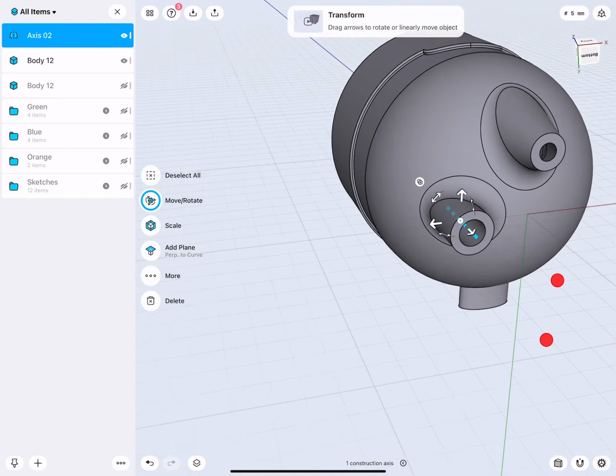Also here, I will extrude this down by 1 millimeter in new body, and this will then be 2 millimeters. Double tap, 3D widget to here, and make a rotation 180. Select both, 60 and 120.